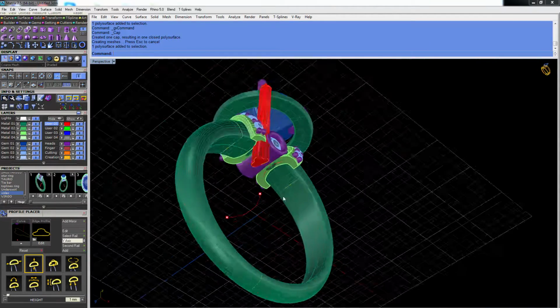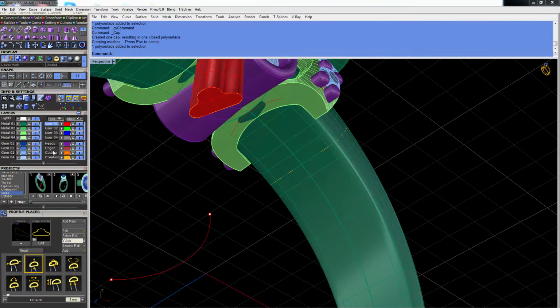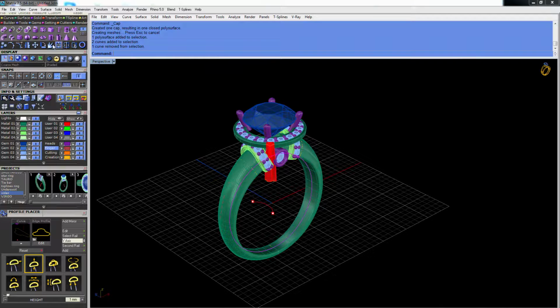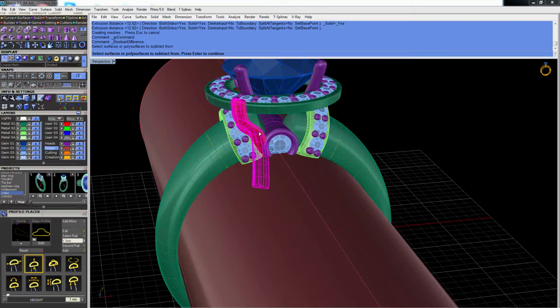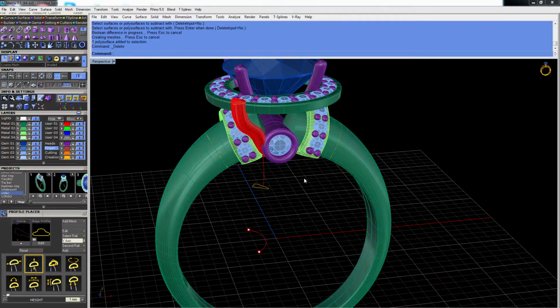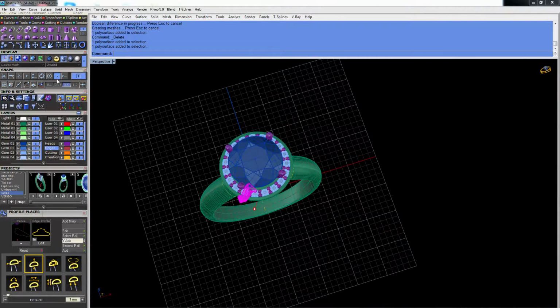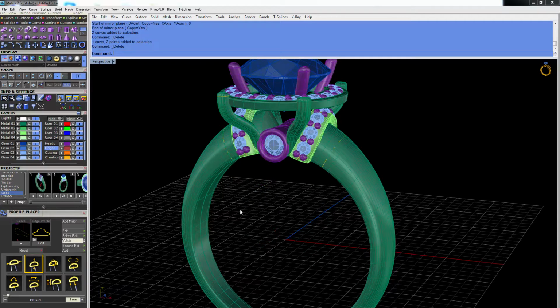So now that we have this, we can just get the ring rail. If we find it difficult to select the ring rail, we can just go here on the finger layer and right click. Well, actually we'll select that as well. Okay, so let's get the ring rail and solid, extrude, make it a solid, and now Boolean difference with this from this. Okay, now that's a metal part, and now we can make mirror to that side and mirror to that side. Okay, quite good. There's just one thing left. Now I'm gonna save.